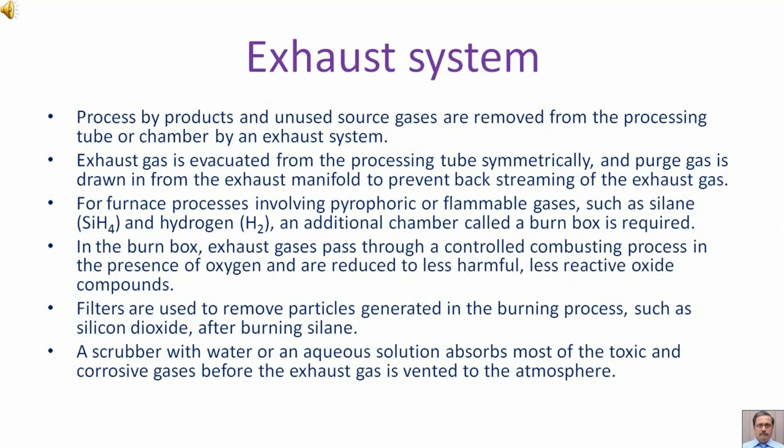For furnace processes involving pyrophoric or flammable gases such as silane and hydrogen, an additional chamber called a burn box is required. In the burn box, exhaust gases pass through a controlled combustion process in the presence of oxygen and are reduced to less harmful, less reactive oxide compounds.